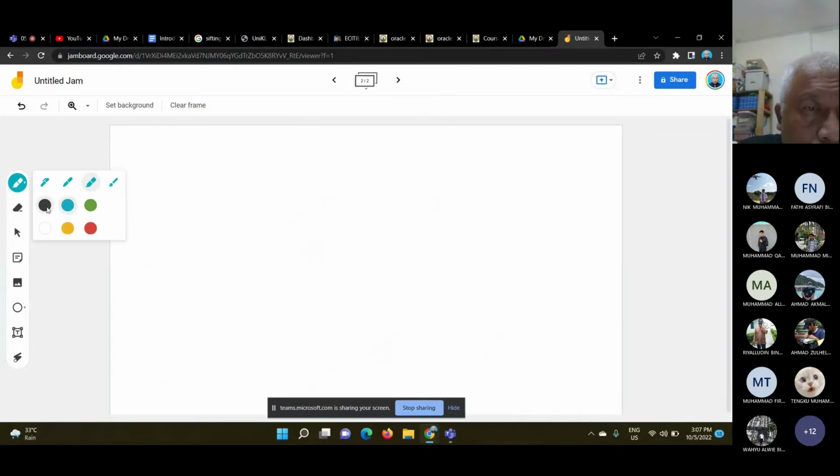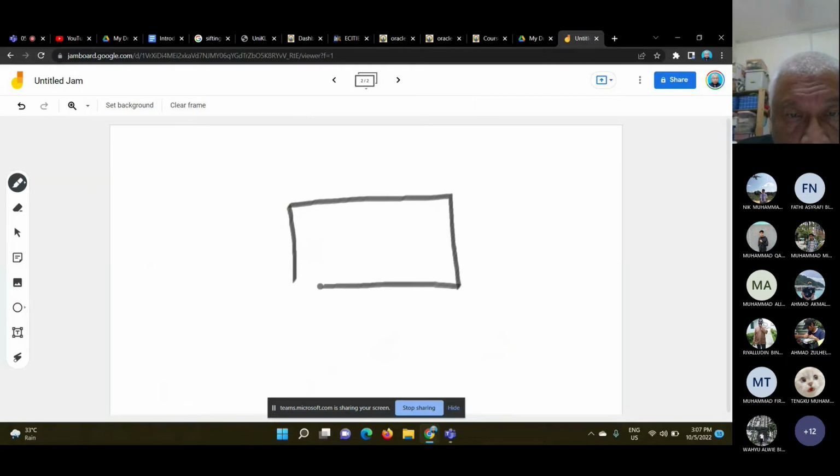So what happens here is when you have this cut, the load that is supposed to be carried this way, say this tension, we have now lost. So for you to determine what has been lost, you also need to consider shear. You need to consider this is tension, say longitudinal tension. You also need to consider shear along this edge.